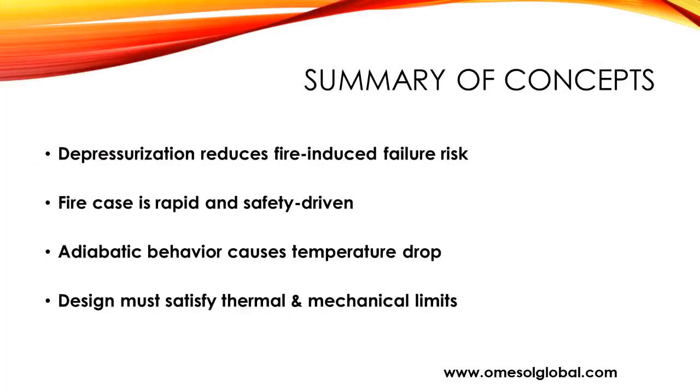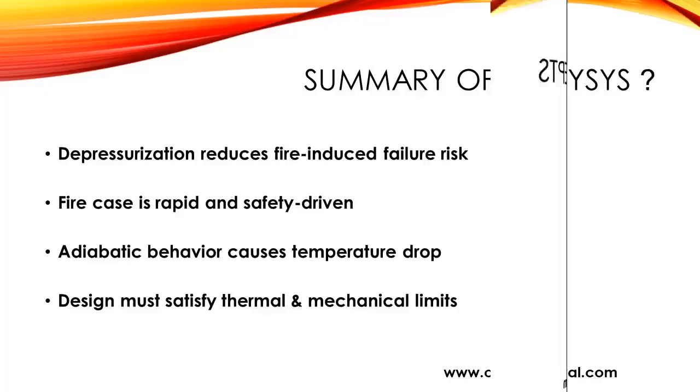To summarize so far, depressurization is a critical safety measure to protect equipment during fire exposure. Fire case depressurization is rapid, typically adiabatic, and driven by safety logic. The design must ensure that both pressure and temperature effects remain within acceptable limits defined by material and mechanical constraints.